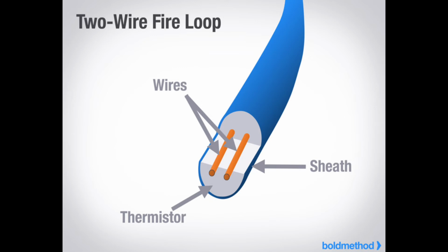Describe the operating principle of a continuous loop fire detection system. One or more wires embedded in a ceramic core inside of a conductive tube. Under overheat conditions, the ceramic core's resistance drops, allowing current to flow, lighting a warning light. How does a thermocouple fire detection system differ from the thermal switch system? Thermocouple depends upon the rate of temperature rise, while a thermal switch depends on a specific temperature.